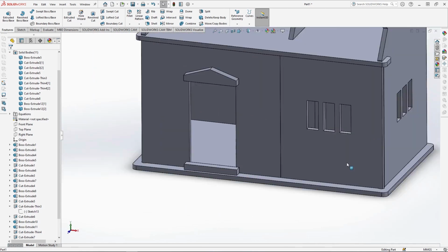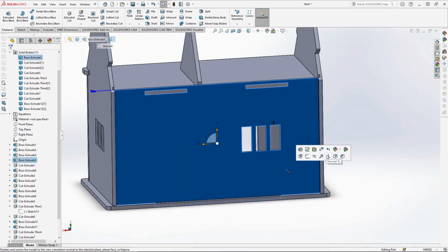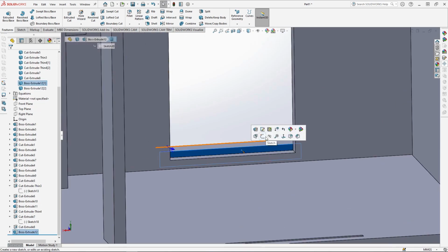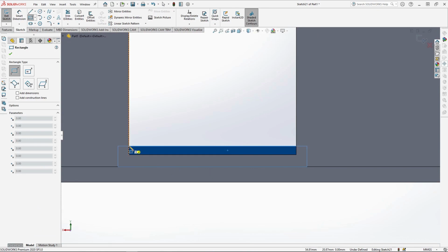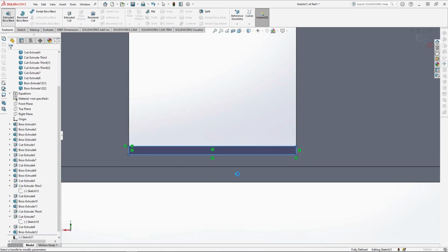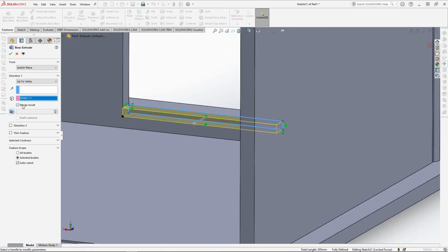To make the step slot onto the door hole, hide the back panel and sketch onto the other side of the step. Trace over the visible face of the step with the rectangle and extrude it by 9mm, merging it onto the step only.